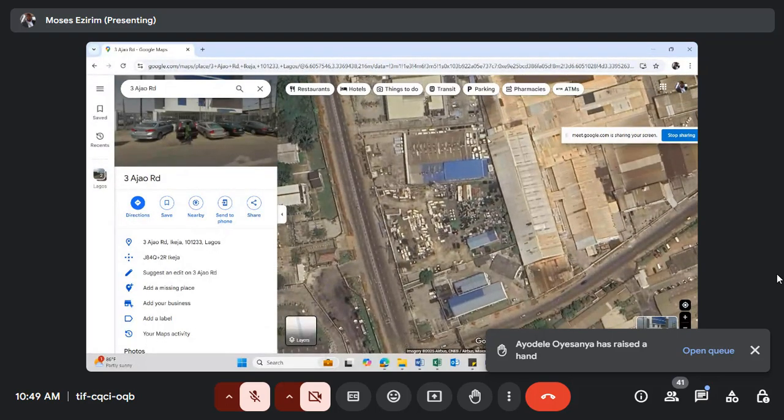Now I want to know what the area of this roof is. Remember, this is the ridge. Can you see the ridge of this roof? So I have this side and I have this side. I want to install my solar panel on this side and on this side, so I will need to know the area of both of them. I will start with this side. What you need to do is come to the edge of this roof. This is it. Can you see it?